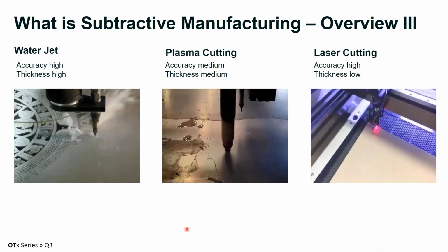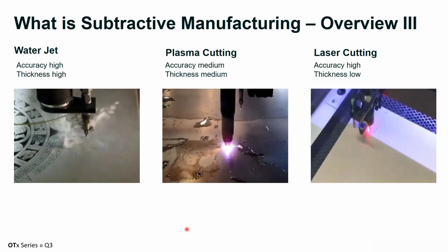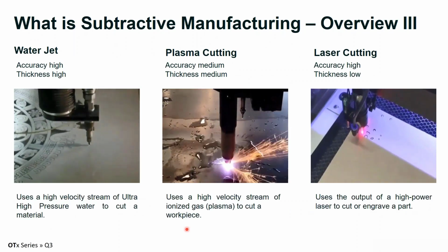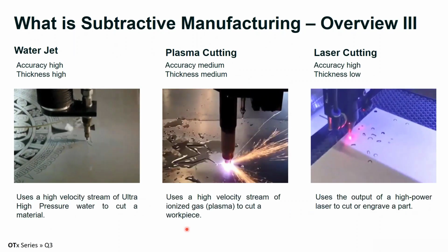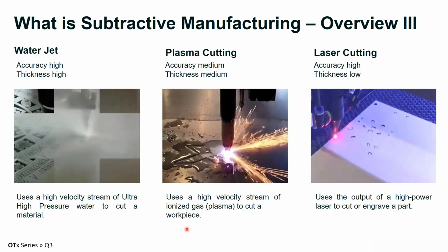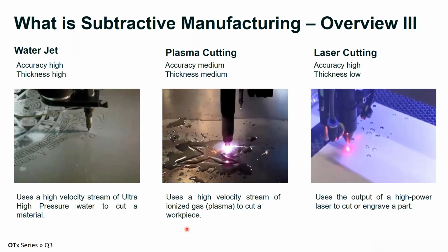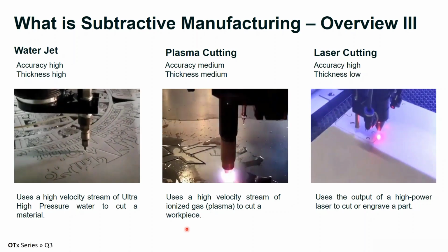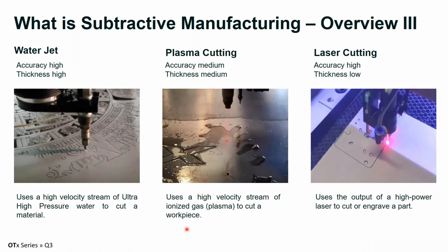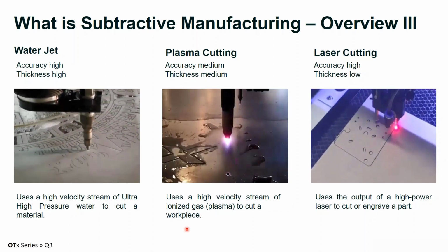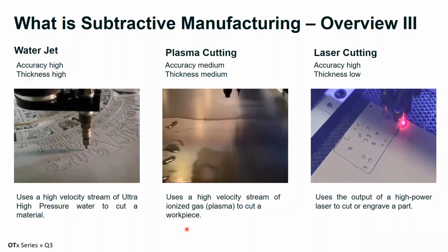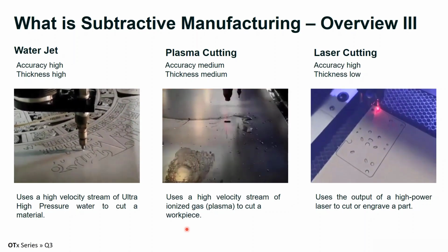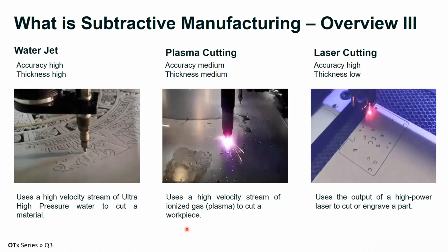For cutting, we have water cutting, plasma cutting, and laser cutting. But from a programming perspective, it's almost the same. It is similar to a 2.5 axis CNC milling, and we rely on some features in the controller to handle the cutting condition. But it's possible to handle water cut and plasma and laser cutting with the HSM product. And also, of course, we can do some wire EDM if that is needed.